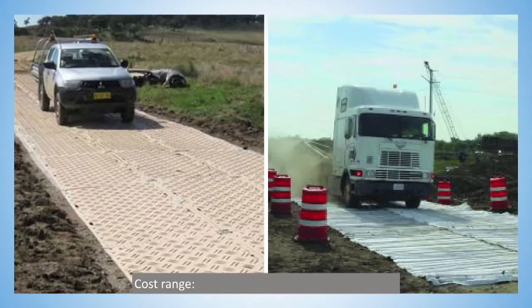Other devices. There are interlocking mats, usually made of either some type of rubberized material or a plastic. The one on the right is called mud mats. It was developed originally for equipment to access golf courses without tearing it all up, so they could move some landscape or make a repair. It is a geotextile fabric with half pieces of bamboo cut into it, and it comes in a roll, and you roll it out. It is not a long-term device, it's just for short-term access.